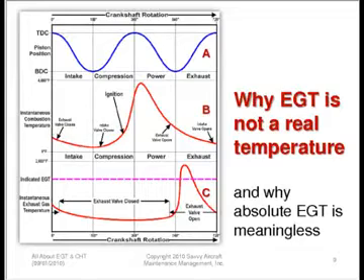And then after the exhaust stroke is over, the exhaust valve closes, and now the EGT probe sits there for 2/3 of the time not seeing anything. So what the EGT probe is seeing is short pulses of rapidly changing gas temperature, punctuated by long periods of nothing. And of course the probe, which has a fair amount of thermal mass to it, is trying to integrate all of this rapidly changing temperature stuff, and it settles at some indicated or equilibrium temperature, which it dutifully reports to our EGT gauge.